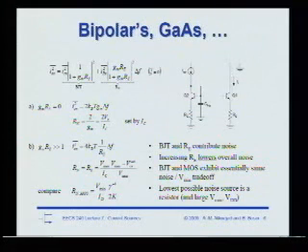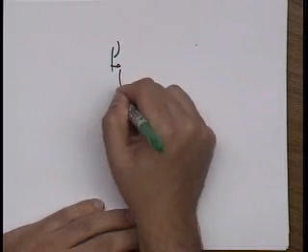So in some ways, I can really relate this expression to the headroom, right? I can say that RE is basically constrained by the minimum voltage that I'm able to tolerate. So I can write RE as V min minus VCE sat. It's always hard to use slides, so let me just draw here.